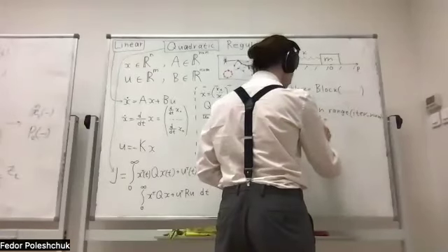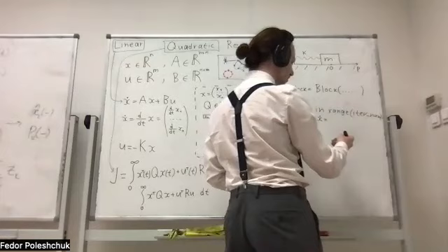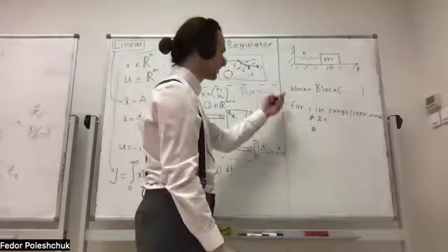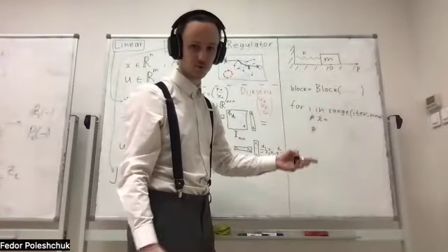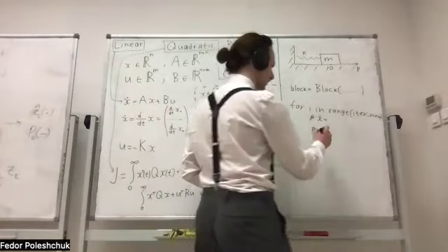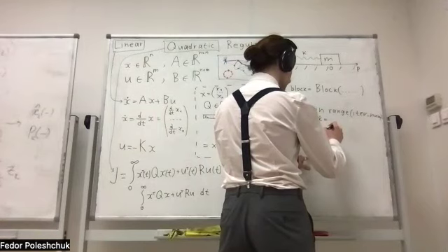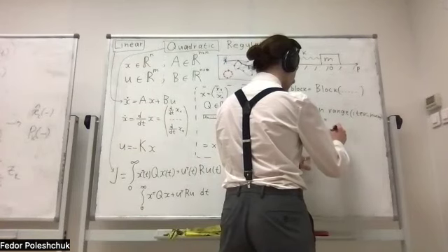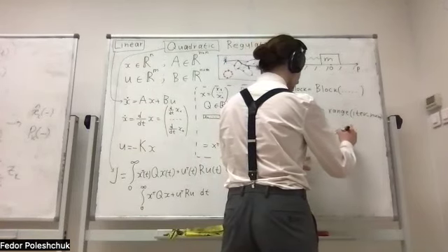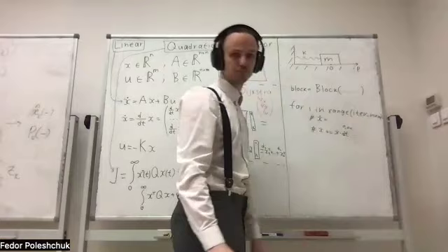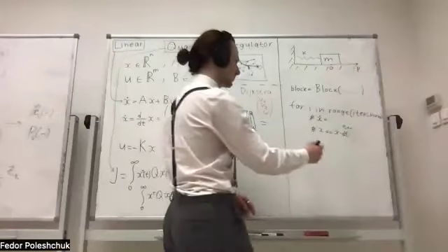After that, the second thing, you will have to integrate this using Euler's method. So we're dealing with the discrete approximation of the system, not with the real continuous system. And we can say that X will be equal to X plus X dot times dt. dt could be, I don't know, 0.01 or something like that. This is just the simulation. So this is the first part.